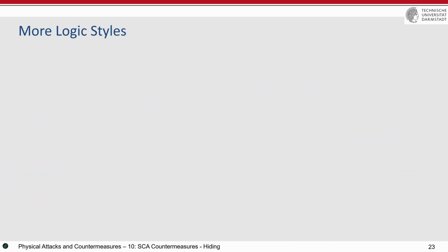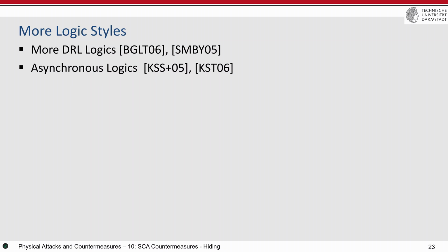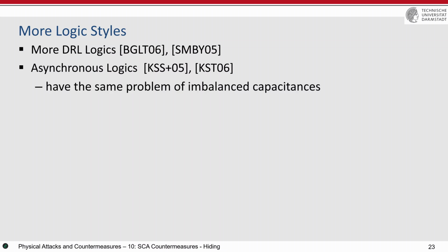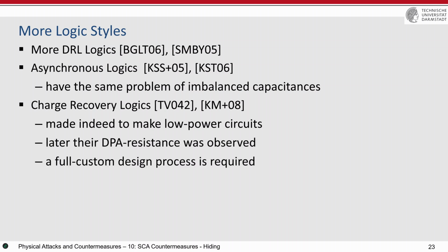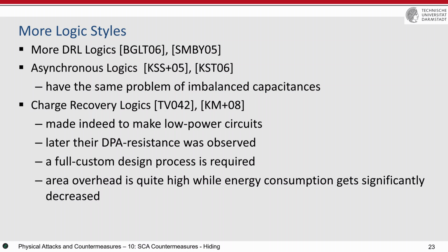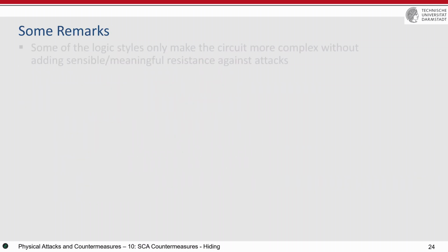Now, there are some other logic styles, asynchronous logic, some charge recovery logic. They are based on some other concept to use the energy which is stored in the capacitors and reuse it and so on. Most of them need a full custom design process because they change the structure of the AND gate and fundamental gates, and they have very high overhead and energy consumption.